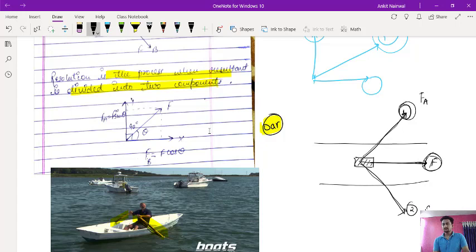So this magnitude comes from these two components. So we need to divide this resultant force into two components. So how will you divide this resultant force? There is a simple concept that the component that is having an angle theta with the resultant force, suppose FB, this is B body, second body is having an angle theta with the resultant force. So this component will be resultant force dot the cos theta.